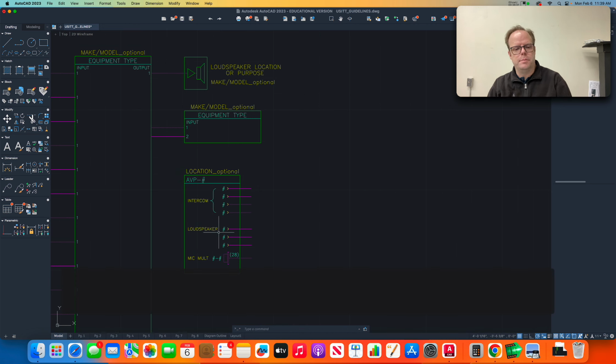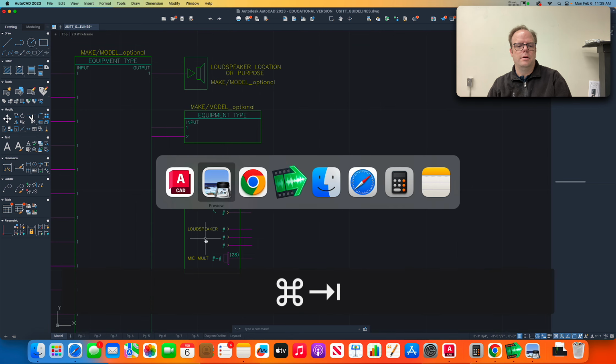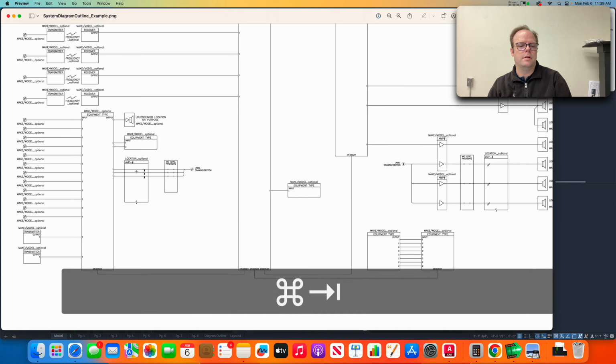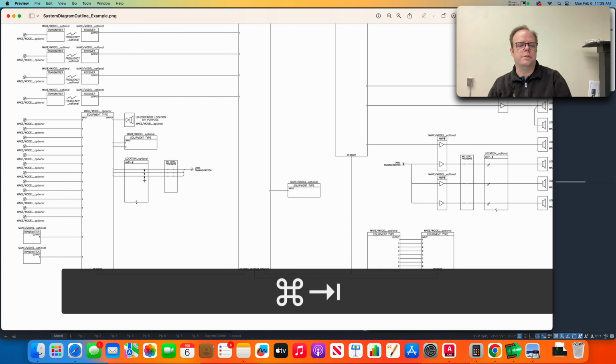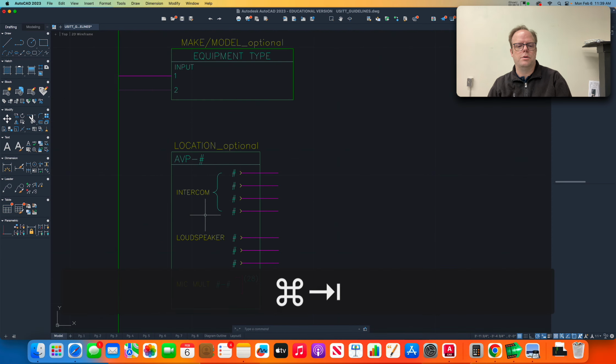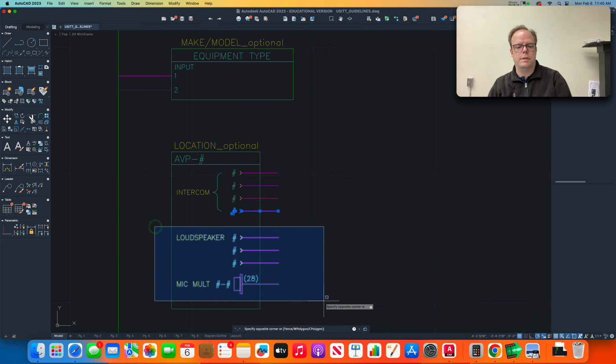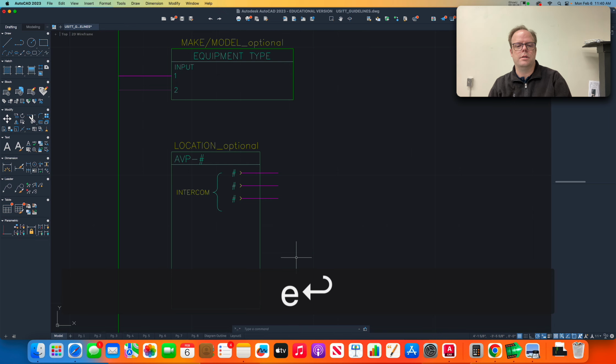And I got to clean this up a little bit, don't I? What do I have to do to it? All right, well, I only need the first 3 lines, don't I? So I can get rid of that, and I can get rid of everything else. So if I just select those things and hit erase, E, enter, I can get rid of those.